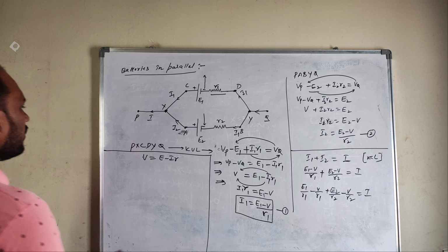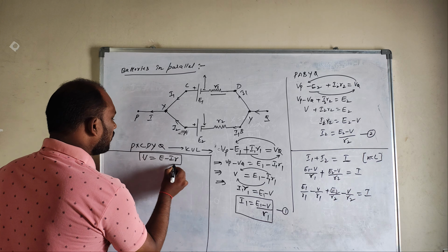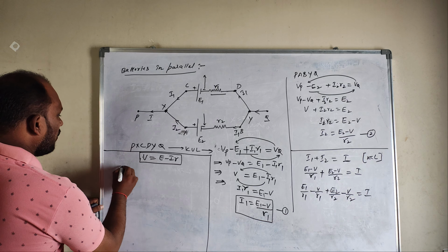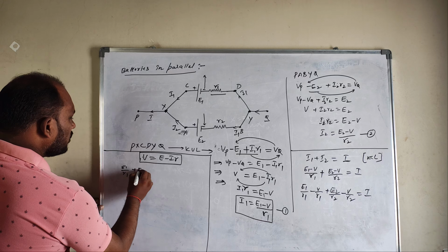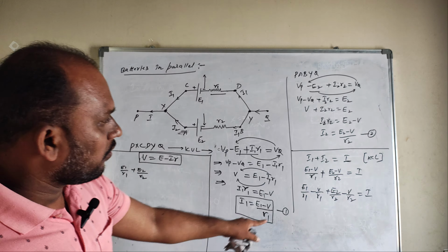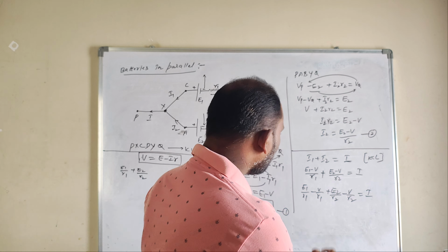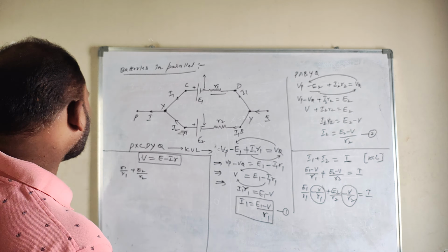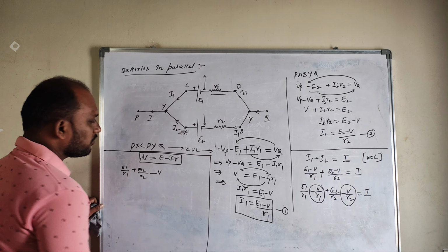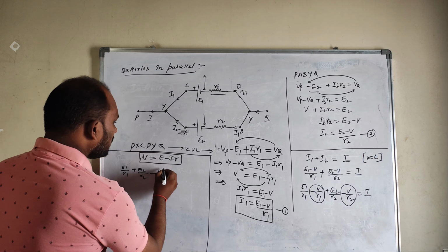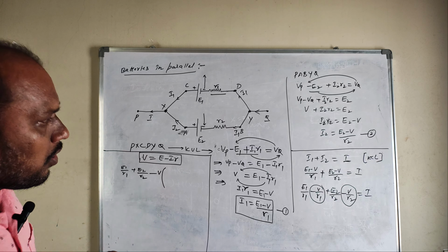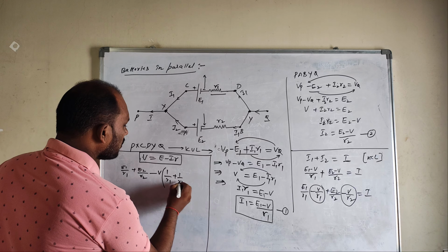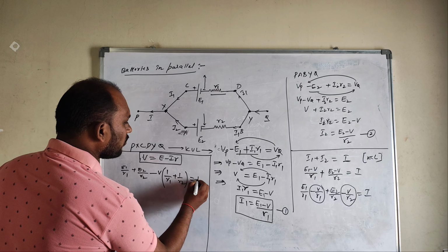Let's see, guys. I want to transform that equation to this manner, so let us see what we get. V1 by R1 plus V2 by R2. Next, what is remaining, guys? This is the remaining part. I take minus V as common, don't worry. Minus V is equal to, next, the part remaining: 1 by R1 plus 1 by R2, is equal to I.